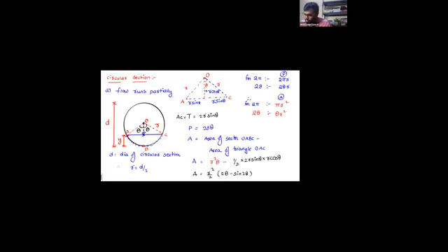So what is the hydraulic depth? You can simply write it down here. So you know that hydraulic depth D is equal to A by T and R is equal to A by P. So don't worry about keeping the values because they are not going to be cancelled down. You can observe here, my dear students, which is going to be constant? You see top width, wetted perimeter and the cross section area. What is constant over here? R. The radius of the circular section is going to be constant. Yes or no?